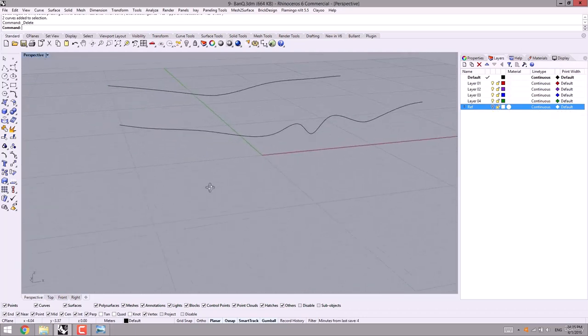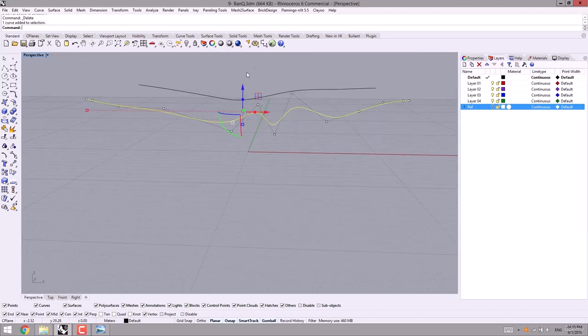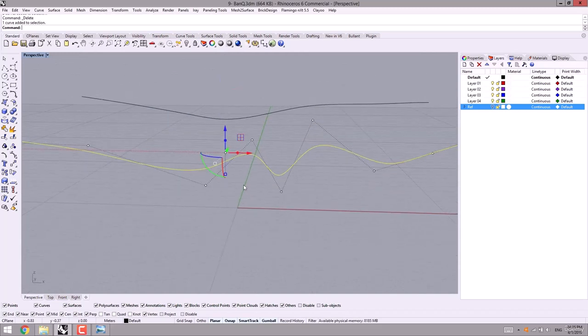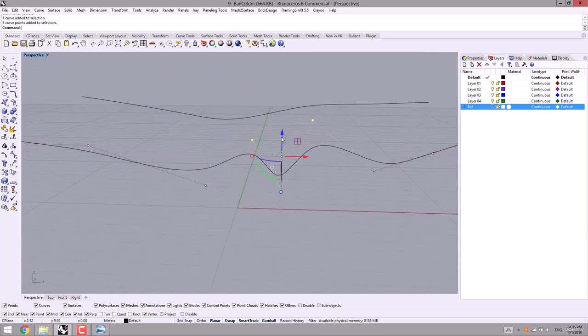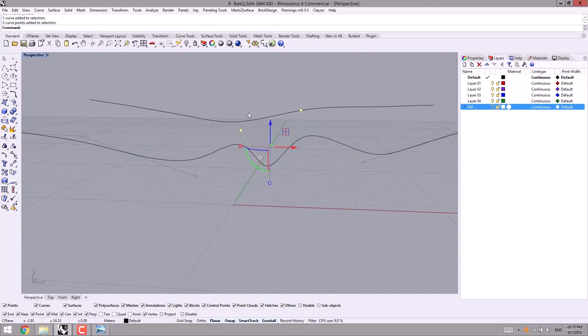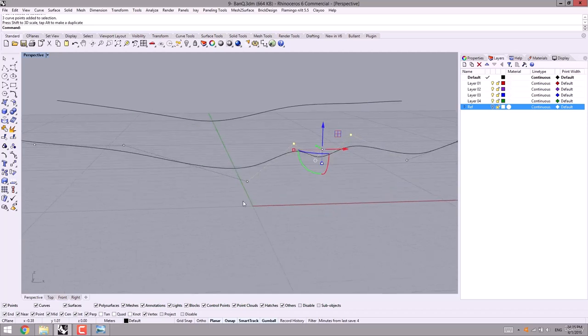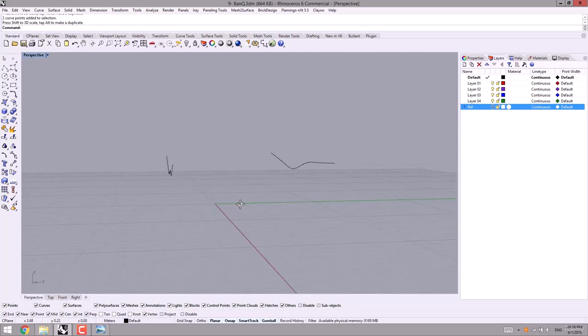Then in the perspective view, following that, we're going to revise the control points and then control the continuity. I select these 3 points and then I use scale, and I make them close to each other along the z-axis. And also these 2 control points, check it out. Well done.